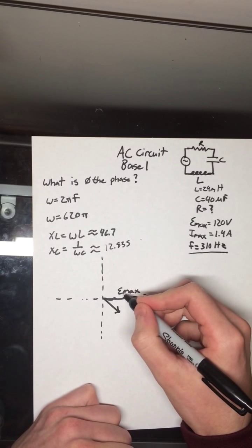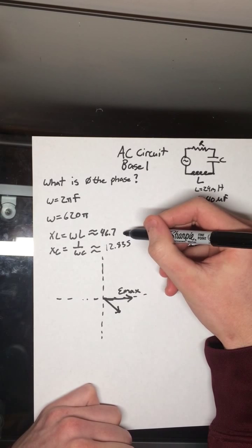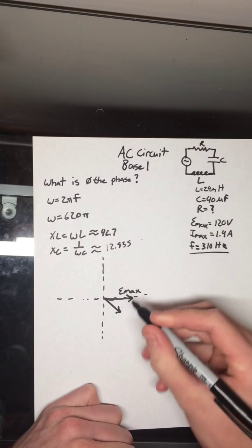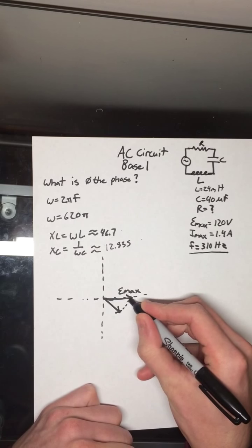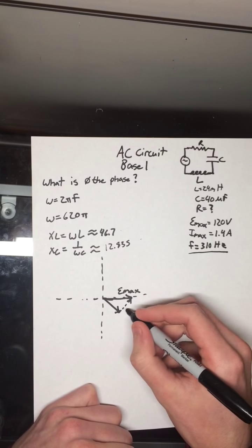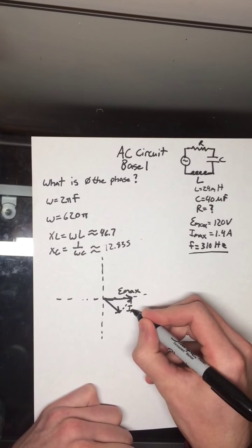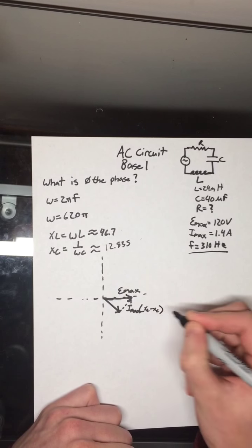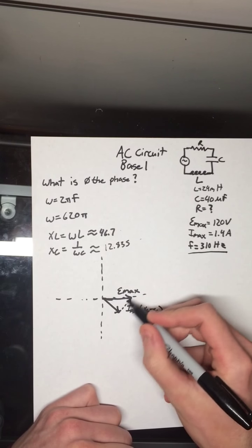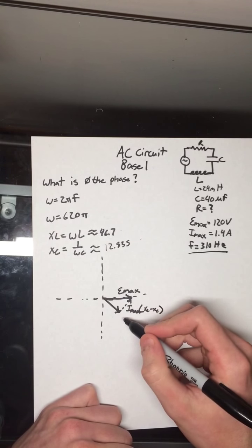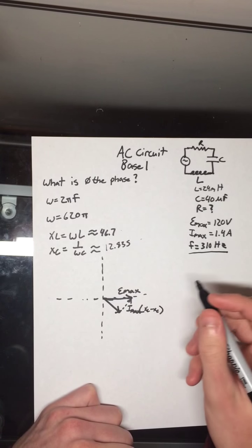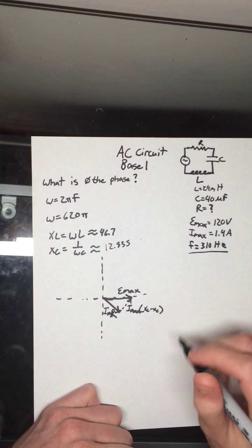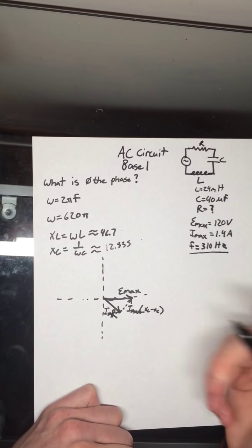And this is true because since the resistance through the inductor is greater than the resistance in the capacitor, then we have this projection line right here, which is going to be Imax times XL minus XC, and as you can see, XL is greater, so you're going to get this vector that points to the maximum generator voltage, and we know that this equals Imax R, just the maximum current and the resistor there.